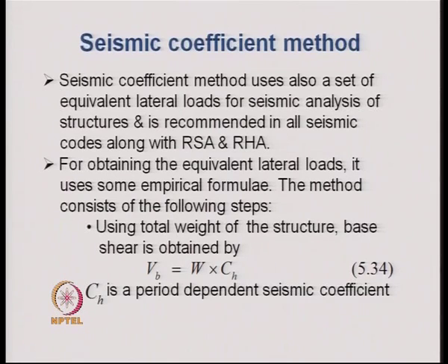The time period of the structure is obtained with the help of some empirical formula, and the mode shape, or the distribution of the load along the height of the structure, is obtained with the help of again some empirical recommendation. Therefore, we do not require the mode shape for the structure.